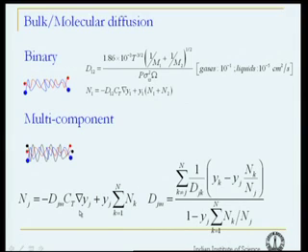DJM is actually not a true binary coefficient, because when you have more than one component, A, B, C, let us say, or 1, 2, 3, we have binary diffusion coefficients between 1 and 2, 1 and 3, 2 and 3 and so on. All those things put together will determine what is called the effective diffusion coefficient.